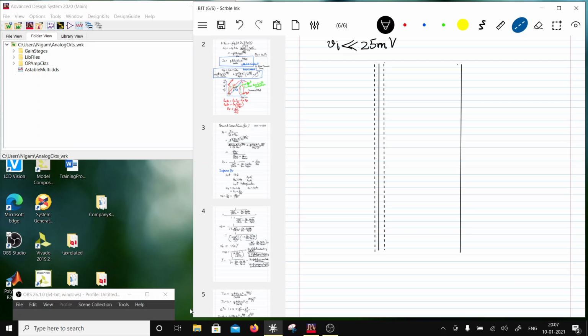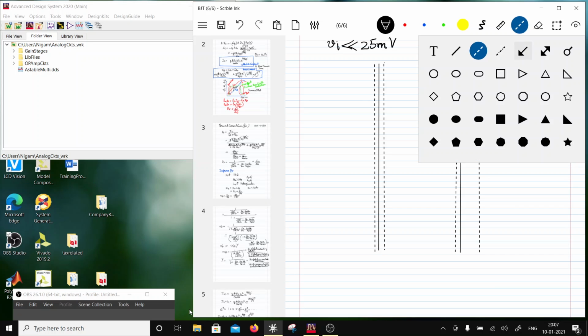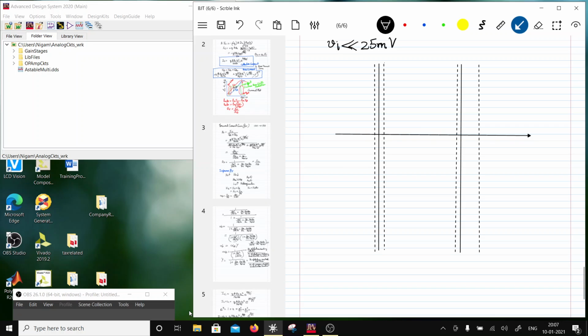And then this is heavily doped, so we have some depletion of the reverse bias collector base junction in the base, and most of it is in the collector because the collector is lightly doped. Okay, and then let's consider this to be the direction convention for current, this direction is reverse of X. So what do we have here?